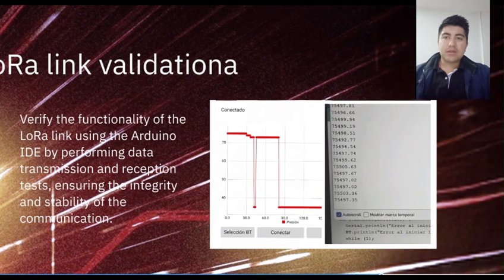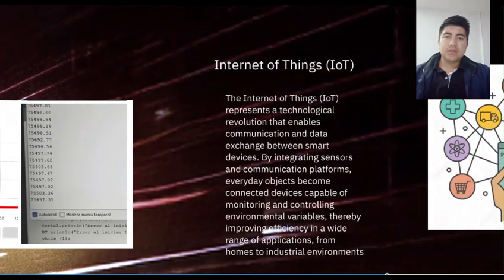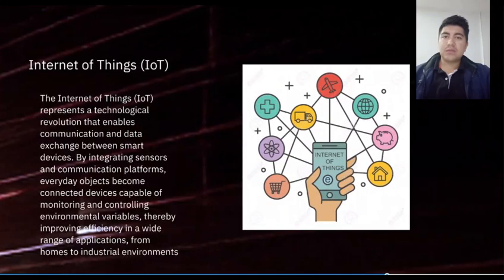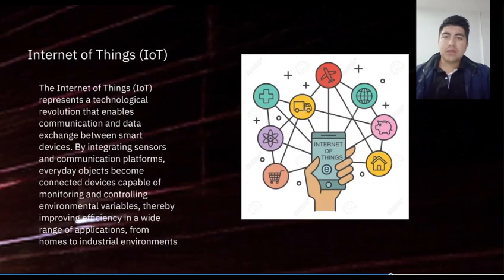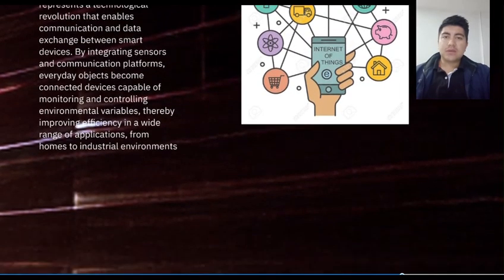For programming of the receiver mode, the Arduino Uno receives the LoRa transmission using the LoRa library. The program configured the frequency, bandwidth, and power. The reception was continuous, and the average delay of 250 milliseconds was suitable for real-time monitoring.